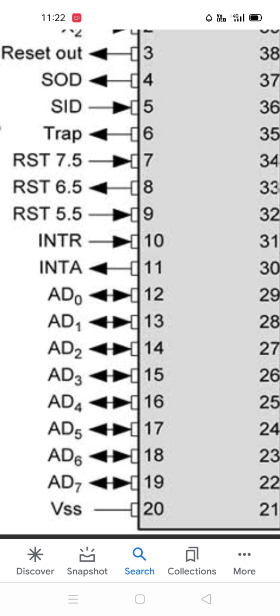Because reset signals are usually sent to all the registers, all the peripheral devices, all the other things which are connected, like memory device, IO device and other things. Everything is done through the reset signal. When the microprocessor first comes up, it sends all the reset signals to the different elements and then only starts its cycle. Okay.